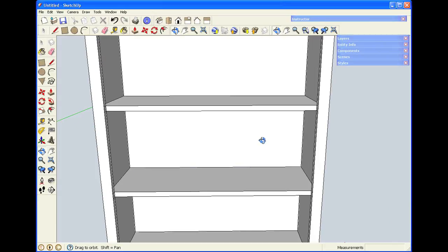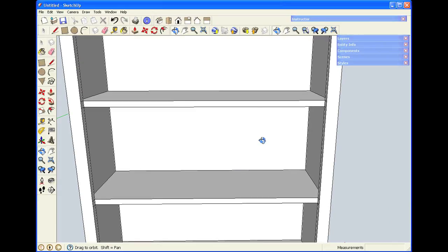make the changes. In SketchUp, it's pretty easy to change things, and because parts are components, changing one part will change other ones. So let's start by putting the new rail in place. If I hover on that width and then come down, I can type comma 1.25, and I'll create a face that's the width of the space in between, and then 1.25 inches in height.